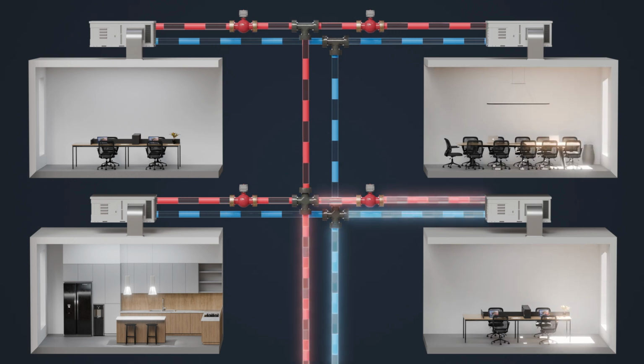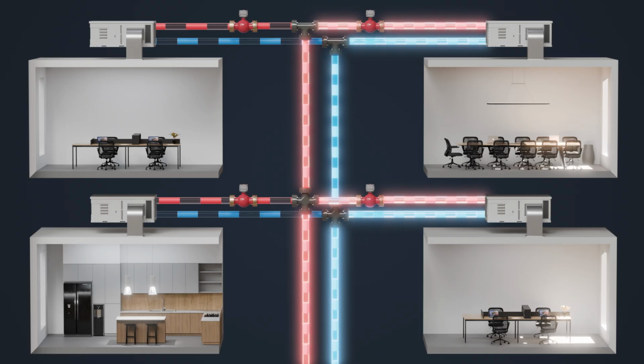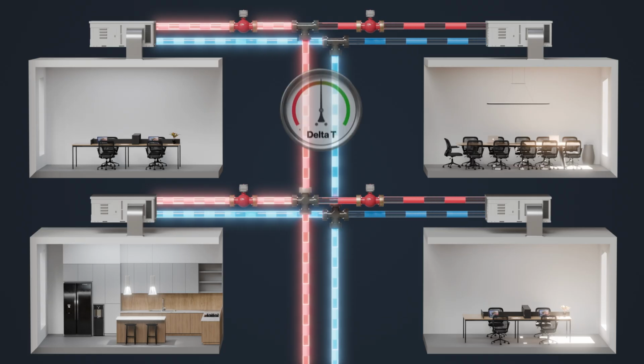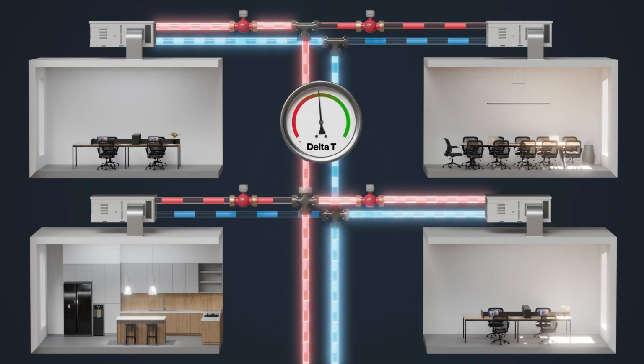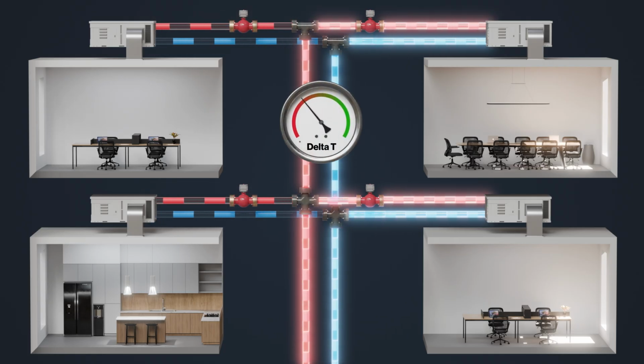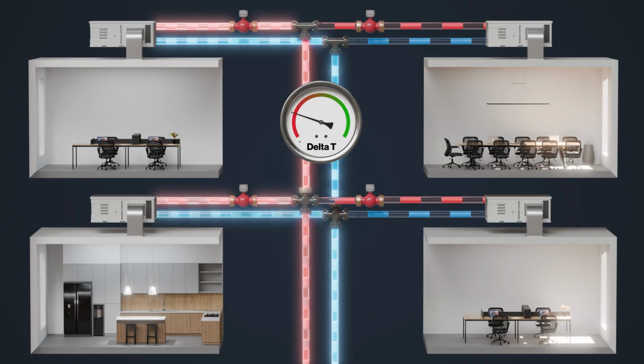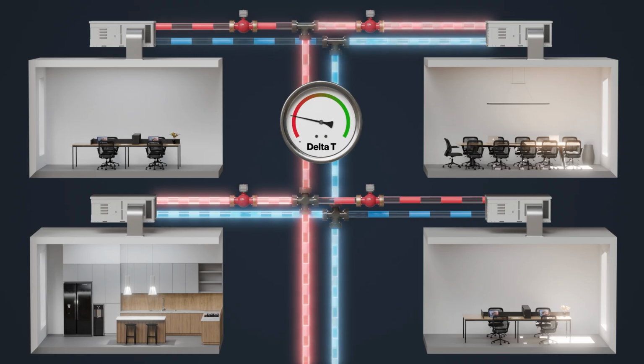But when one pressure-dependent valve changes position, pressure changes ripple throughout the system. Flow through other control valves and coils changes unintentionally. Other valves react in turn, again and again. The entire system is in a constant state of flux. This flow instability reduces heat transfer effectiveness and increases the required flow rate, ultimately delivering a lower delta-T.